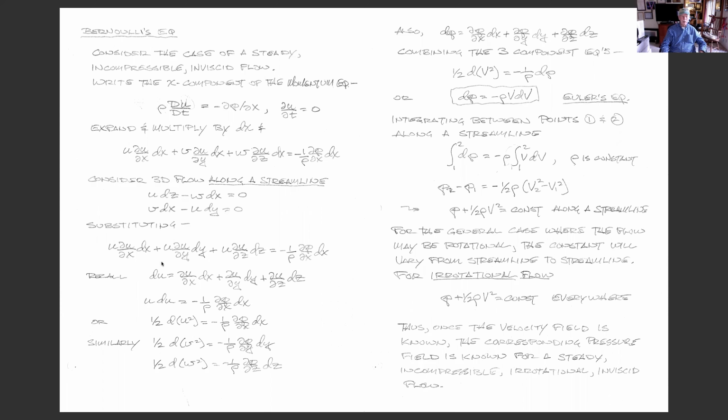But the second term, I changed stuff. And the third term for irrotationality. You can check the algebra on doing this. I didn't mess with this term. But what I have now is u partial u with respect to x plus v partial u with respect to y, plus w partial u with respect to z, just replacing via these terms. Here's how I got rid of the w, and here's how I got rid of the v. So now everything is in u.